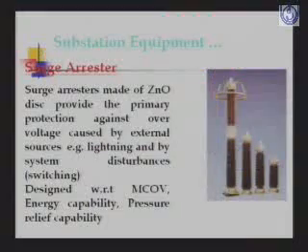Then we have the surge arresters in the substation. These surge arresters are made of zinc oxide disc and provide the primary protection against overvoltage caused by external sources like lightning and by system disturbances. These are designed with respect to energy capability and pressure relief capability.